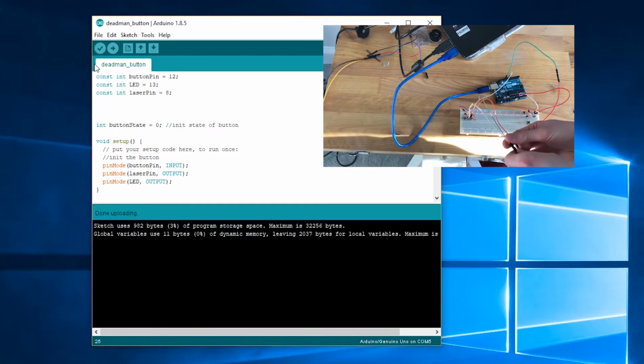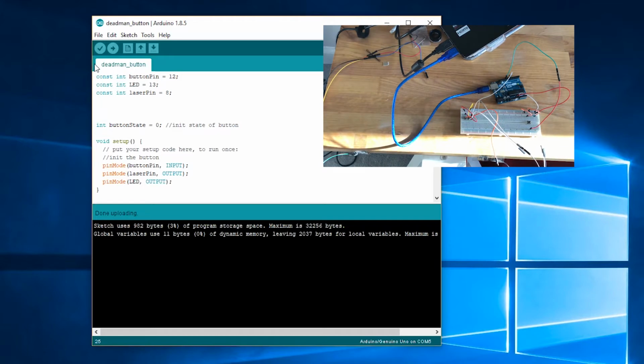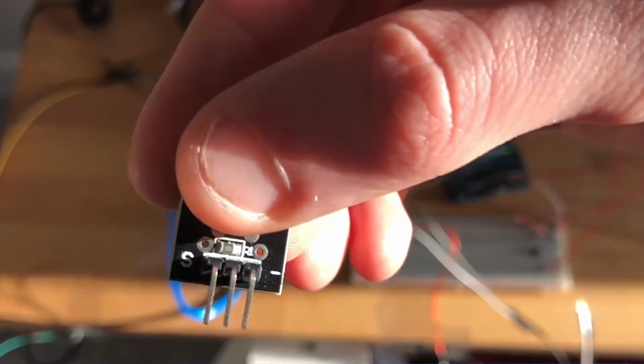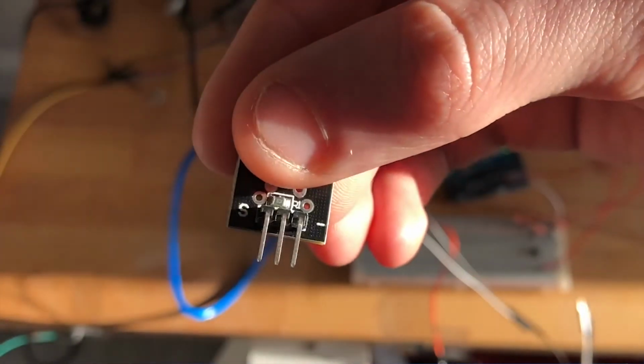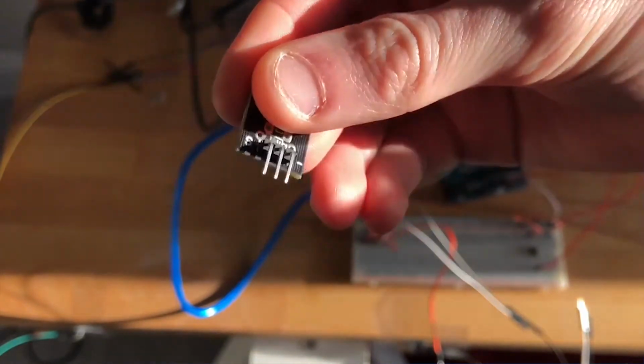And before I start that, I'm just going to unplug the power and the earth, or the ground. So I'm going to do black and white from my laser, so that even if something happens to the button, as I said, it is very sensitive, it doesn't fire. So in the same way as with the laser, the photoresistor is set up in a 3-pin arrangement: signal, power, and ground on the outside. Again, we supply it with 5-volt power,